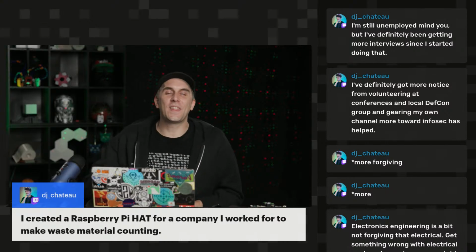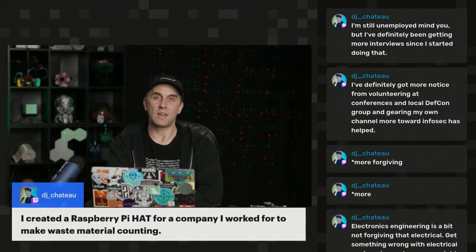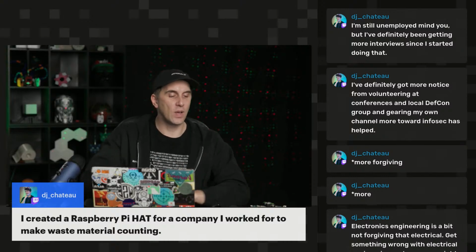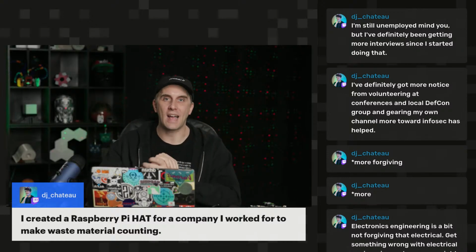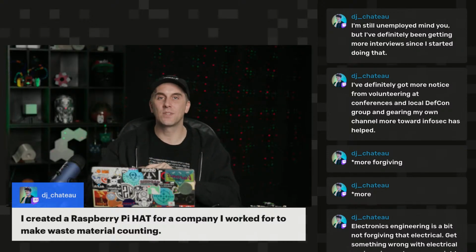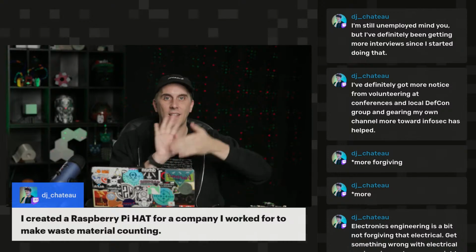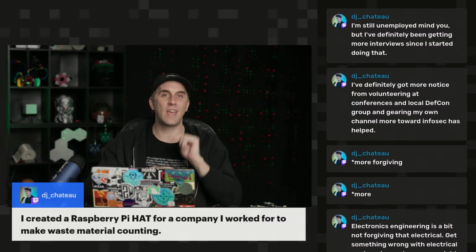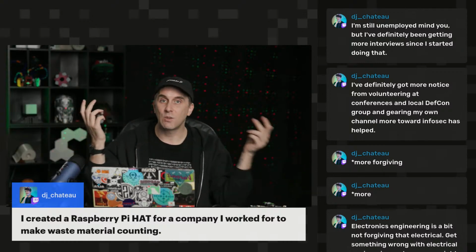So one of the things that is kind of regrettable about these new printers we've been talking about is the fact that they waste a good amount of material. And that's because on every layer, when they're doing a color change, they are going to be purging material. So let's say that you have a box and you want to paint one side of that box green and the rest of it's going to be all black. There's two different ways of doing this when it comes to 3D printing with one of these new Bambu printers. You could turn it on its side and have the green side on its face, facing towards you. And that would cause a tremendous amount of waste. Every single layer, it would need to purge itself at least twice, once for the black filament and once for the green filament. So it would be creating a lot of waste.